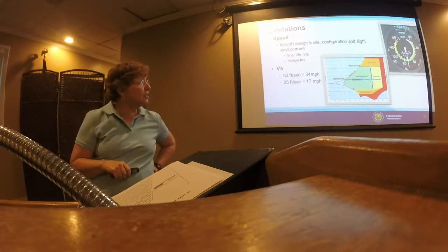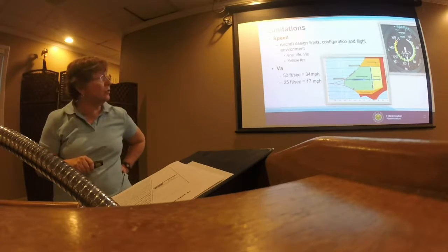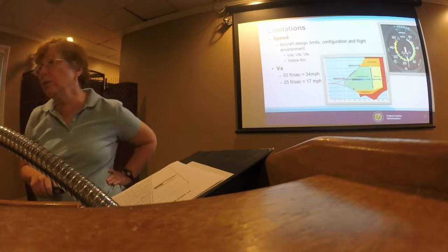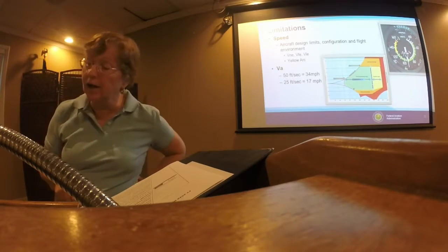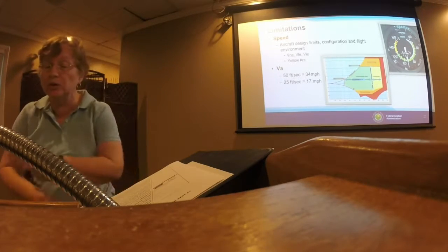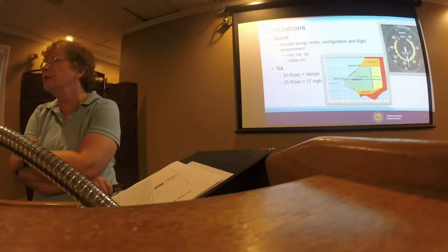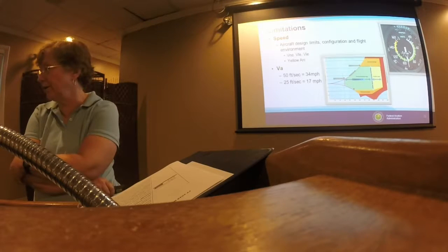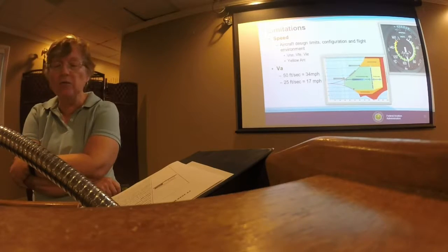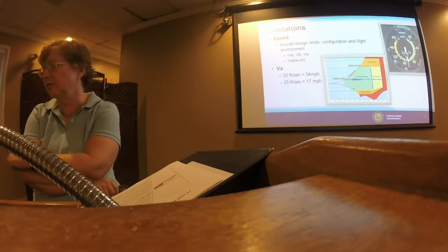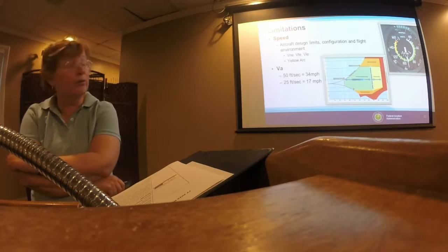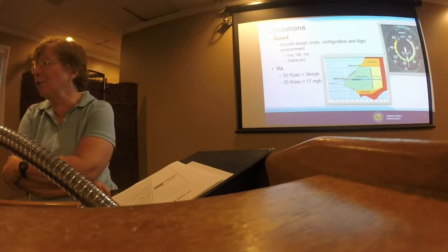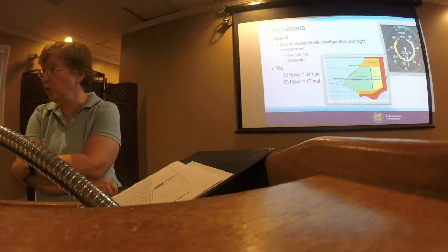But beyond that speed, it's actually 25 feet per second, or 17 miles an hour. And it's actually not unusual to get transient gusts that are that energetic, even with light turbulence. So the guideline is, don't fly in the yellow arc unless it's really smooth.